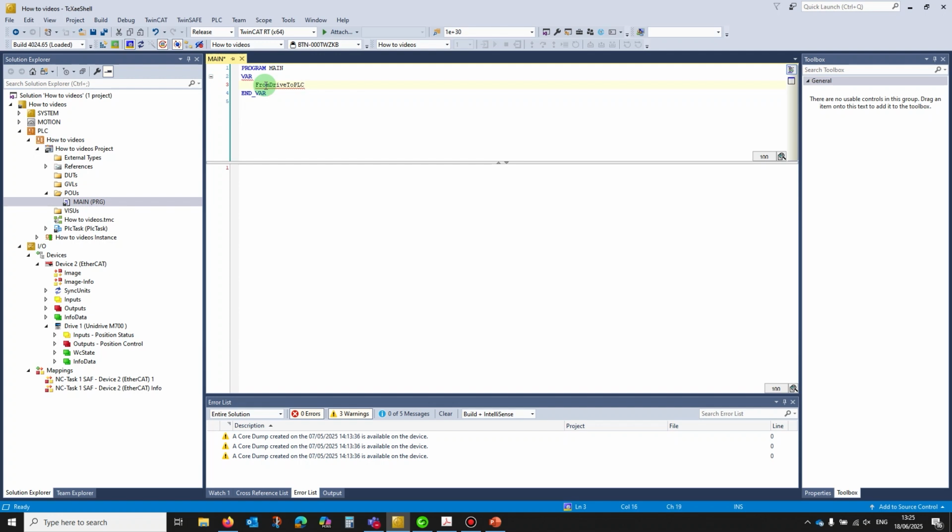Now, when you're assigning these variables, you have to assign them in such a way that the memory location that they use is in a place where the data linking part of the PDOs can see. Okay, so in order to do that, you have to map them manually into I and Q registers. There are 3 sets of PLC registers that have been in PLCs for at least 30 years, and those are I's, Q's, and M's.